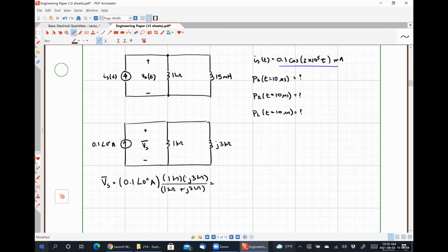I got 0.094 with an angle of 18.43. So I'd be willing to bet that you used ohms as your units instead of kilo ohms.